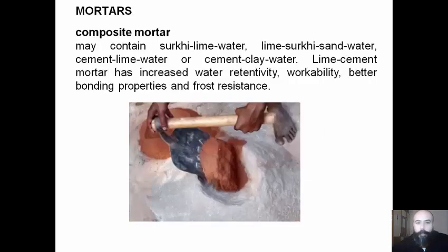Composite mortar may contain surkhi, lime, and water; lime, surkhi, sand, and water; cement, lime, and water; or cement, clay, and water. Lime cement mortar has increased water retentivity, workability, better bonding properties, and frost resistance.